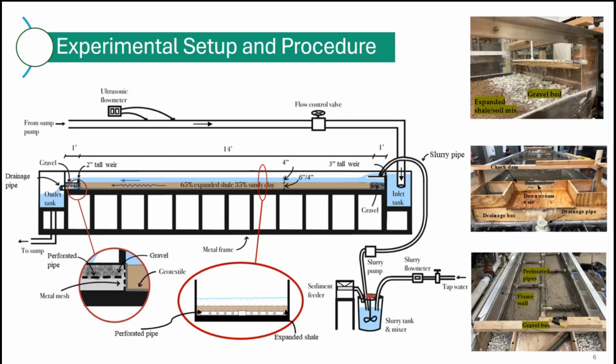At the end, we had a facility to capture the water, but before that, we have a weir. The flow would go over the weir as we have in all our biosoils, and then water would seep through the soil or biosoil, and then we have overflow, the excess flow that cannot seep through, and then we have underflow in this case.